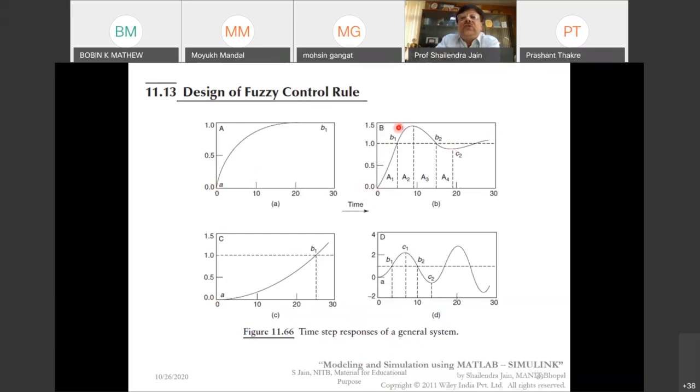So we'll have the overshoot, undershoot, and then we'll settle. This is the unstable system. In an unstable system, our error keeps on increasing and your controller will never reach the settling limit. So any particular step response of any system will have these 4 possibilities. Generally, the most common is that it will start from 0, reach a maximum limit, overshoot, undershoot, overshoot, undershoot, and with some time settle. So you can see we'll have 4 different areas: A1, A2, A3, A4.